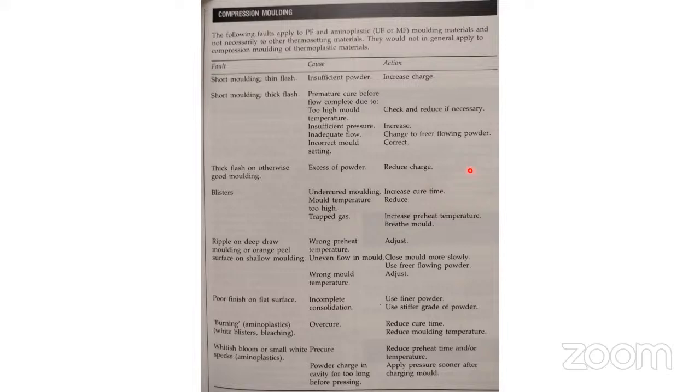We get strength equivalent to sheet metal and formability like a plastic part, and multiple parts we can make as a single part, whereas sheet metal parts have to be welded. So if I compare tooling cost, which one will be cheaper? Compression molding is cheaper compared to a press mold for sheet metal, but time consumption is high.